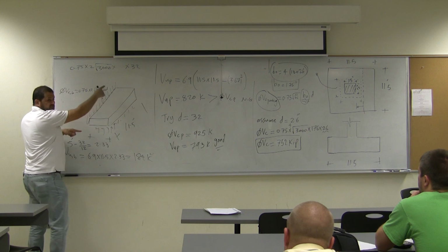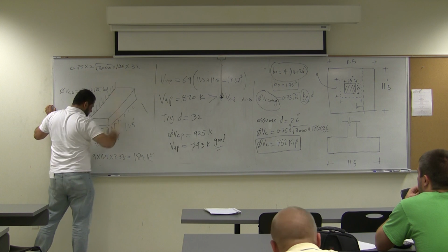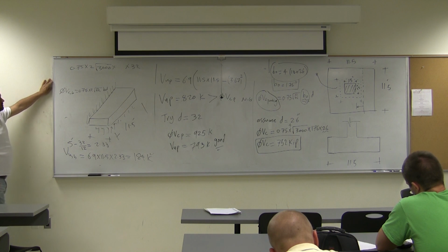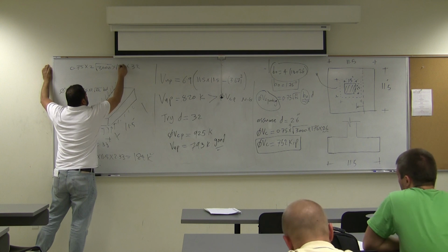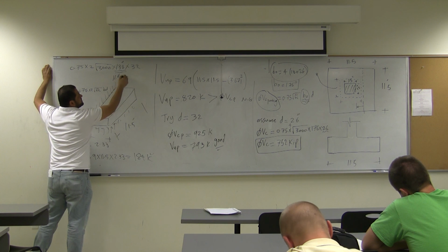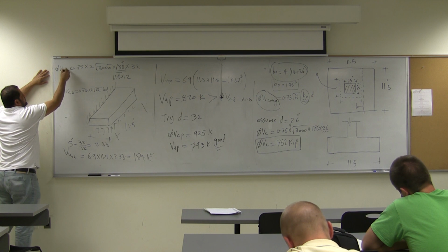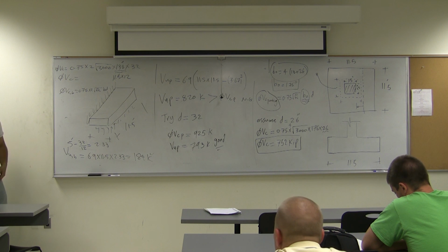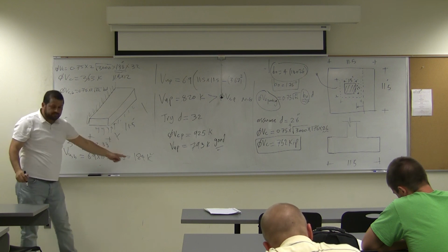So this will be huge, right? It's 11.5 times, how much? 11.5 times 12? 138. This 138 inch, that's B, which is 11.5 foot times 12 to change it to inch. So you got phi Vc, how much? 363. That's a good number. 363. Okay, way bigger than Vu.